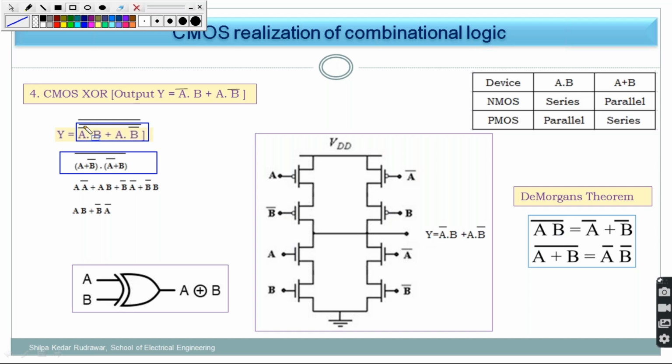So now the complement is present over here. The complement of a sum, because these are individual products and this is an addition. The complement of a sum is the product of complements, and that's why I have written the product of complements over here. Instead of plus there will be into, the A bar will get cancelled, and B bar will be there.